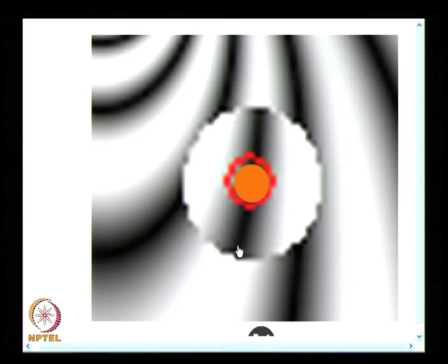I see a fringe. So, that is why I said in all optical techniques, interpretation of recorded data is very crucial. Just because you see a fringe, I can't say this was fringe order 3. So, in all these points fringe order is 3, you can't conclude that way.